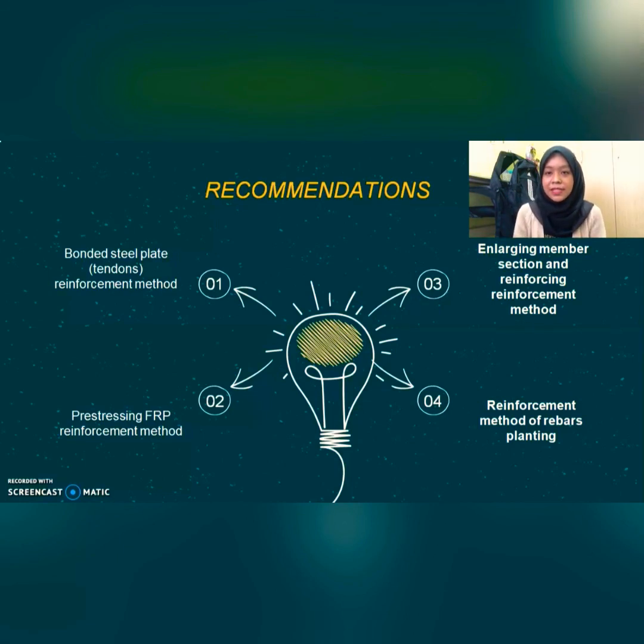Second, the pre-stressing FRP reinforcement method. It improves the bearing capacity of the bridge structure, has incomparable advantages in flexural reinforcement of large span beam slabs, and significantly reduces deformation of the structure, decreasing the crack width and deflection deformation. It is suitable for flexural reinforcement of large span beam slabs. Then it improves the stiffness of the structure and makes full use of the material performance, saving a lot of materials and